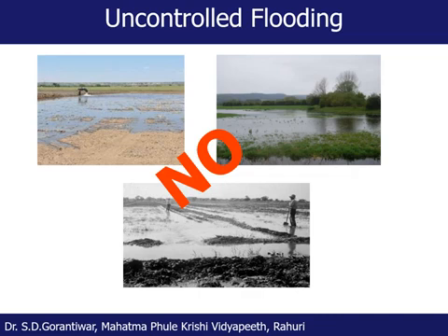And as I told you earlier as well, in surface irrigation method we follow this by allowing the water to move over the land surface. When water moves over land surface, some of the water infiltrates into the soil, stored into the root zone. Some of the water may percolate beyond the root zone, and some of the water moves over the land surface. And while this water moves over the land surface, the water will also be stored in the root zone in the next piece of land actually. So this is surface irrigation method.